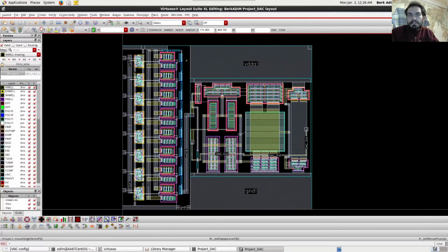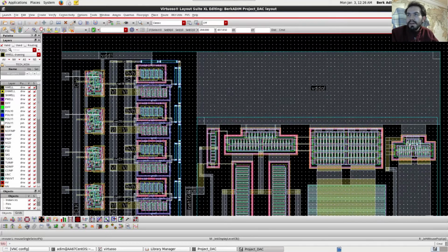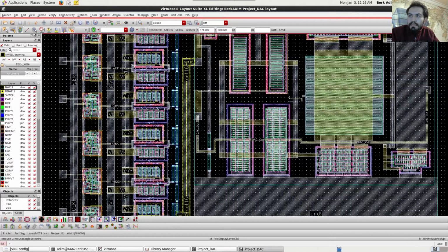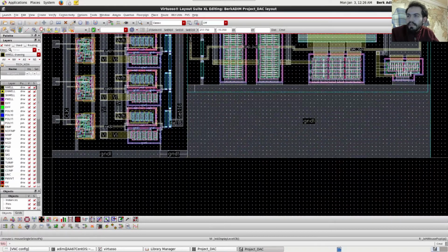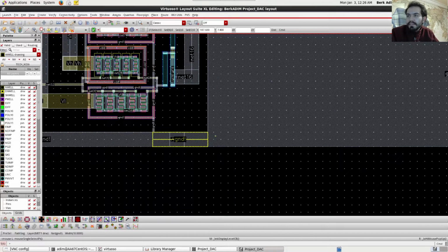Anyways, there are some important design considerations here actually. As you can see, we have split the voltage sources for the digital part of our circuit and the analog part. So when the digital part draws high currents from the supply in transient switching portions, the supply of our op-amp doesn't get affected, so the op-amp output doesn't get affected. And to prevent the same thing in the ground portion, we made a star ground. This is our ground pin here. We made a star ground connection here.